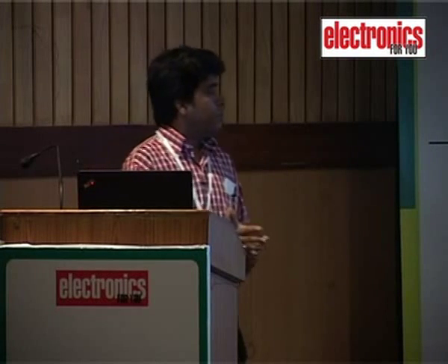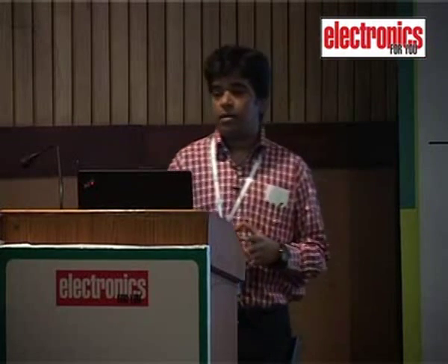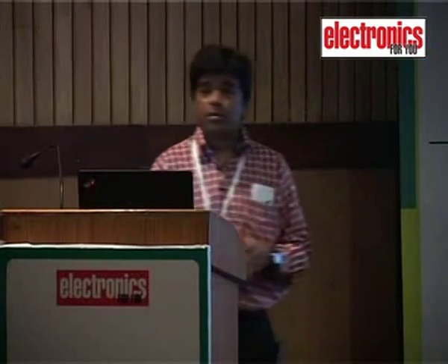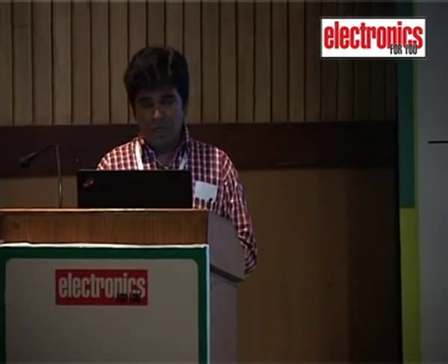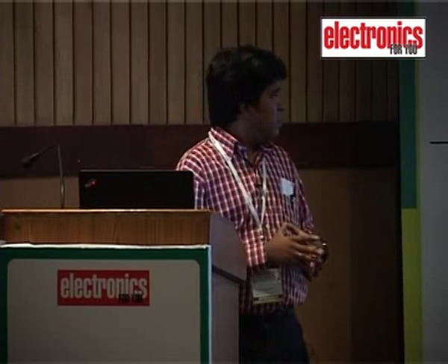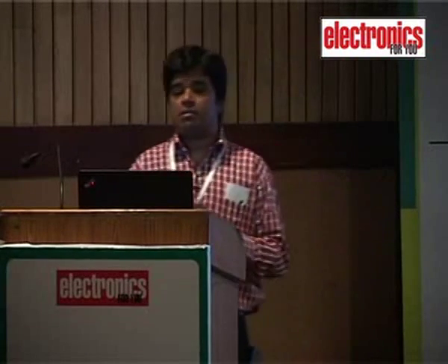So finally, what are the key parameters of our interest? Yes, offset, where our actual image data is lying, width and height of the image, bit resolution per pixel, and image data. Going ahead, I was talking about 8-bit resolution. The 8-bit resolution is very limited. However, a true direct color system is being used for image representation. Our human eyes are capable of responding to and identifying colors distributed over 256 levels using 8-bit. So 8-bit should be fairly enough.